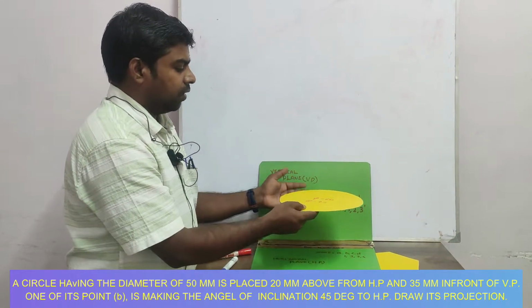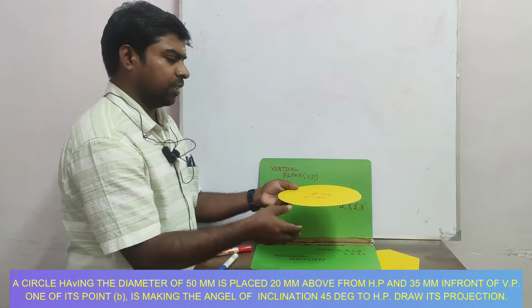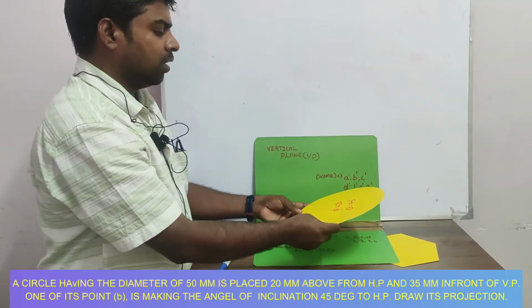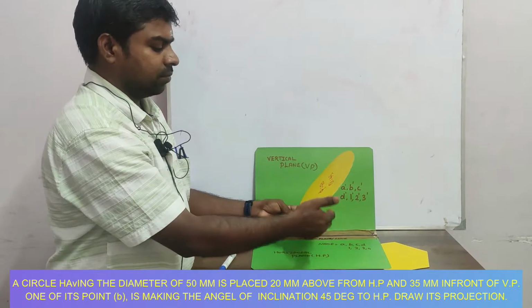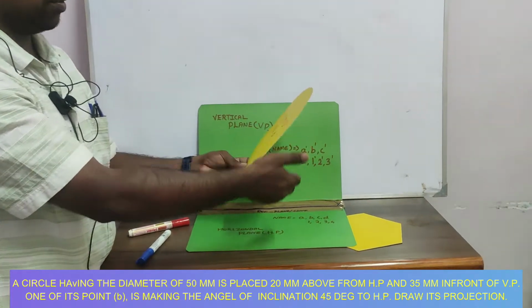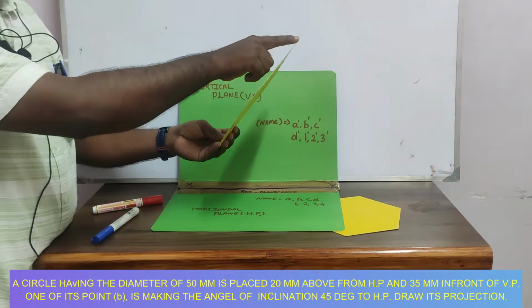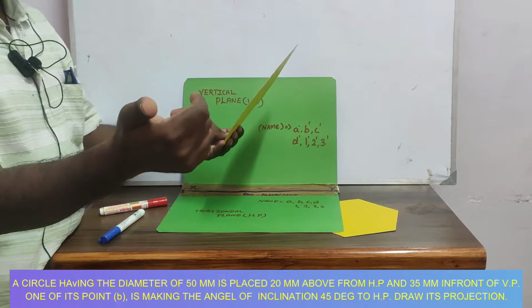Okay, and in front of VP it's 20 mm, or sometimes they may not give any distance, so you can take it anywhere. So you may take it like this if it is so easy. So you will take this problem where it is inclined 45 degrees to this. Okay, 20 mm height and after that 45 degree inclination. So when you are seeing the front view you will get only one line.